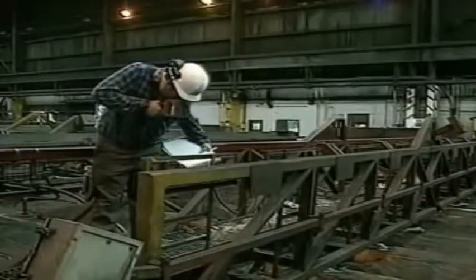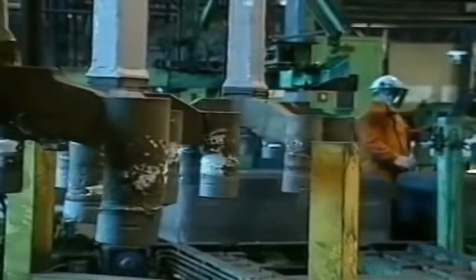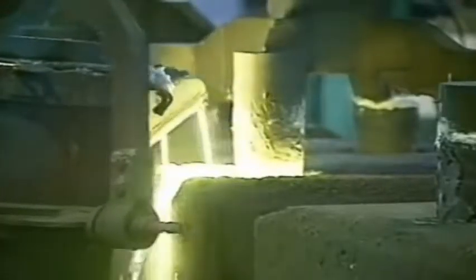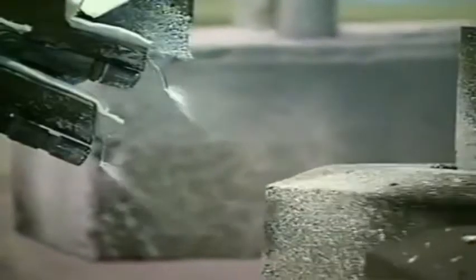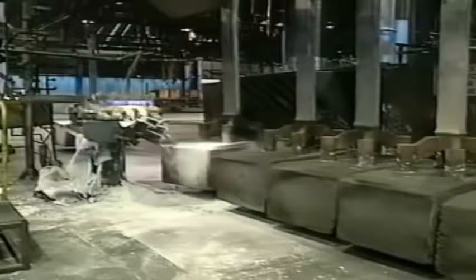The temperature of the pit is important and is checked on a regular basis. The baked anodes are fitted onto steel stubs. These are held in place and connected electrically with cast iron. The anodes are sprayed with molten aluminium to protect the top and sides.